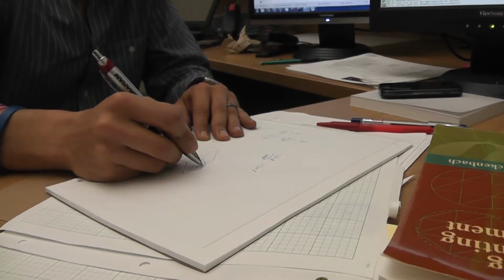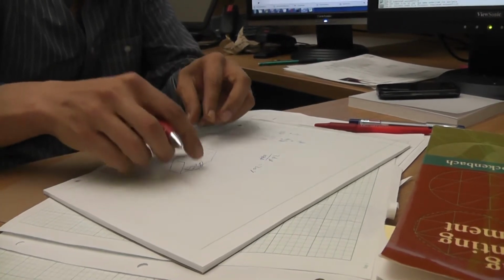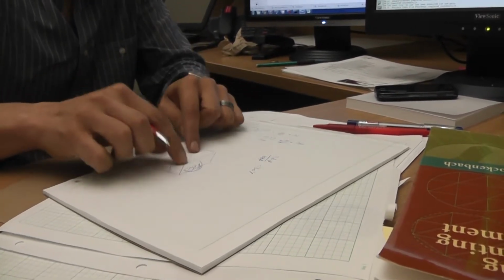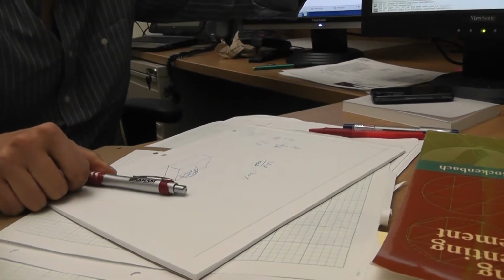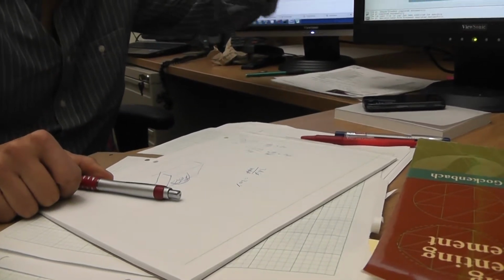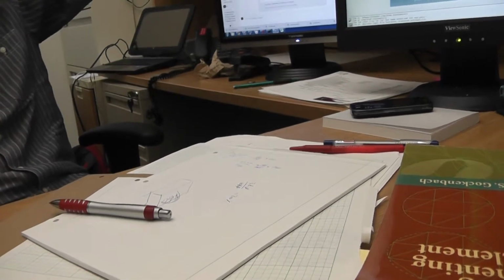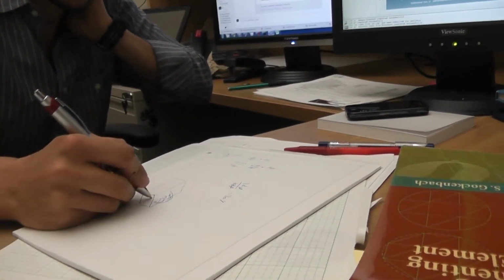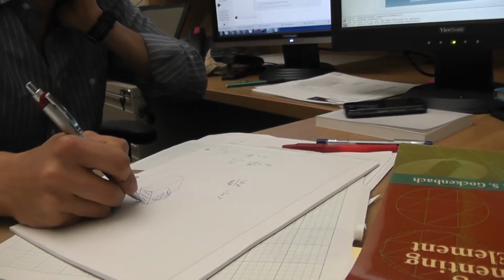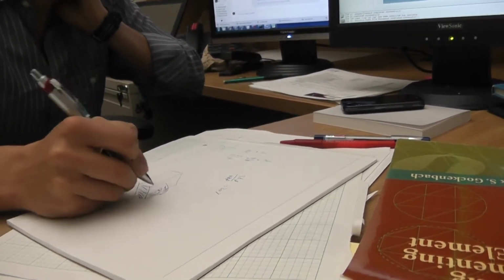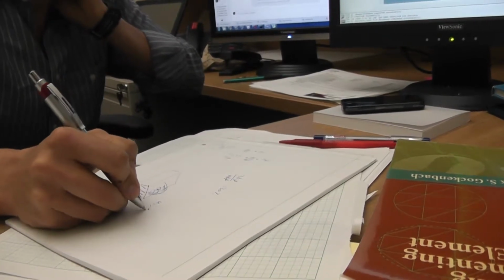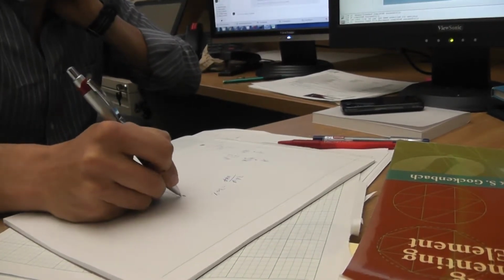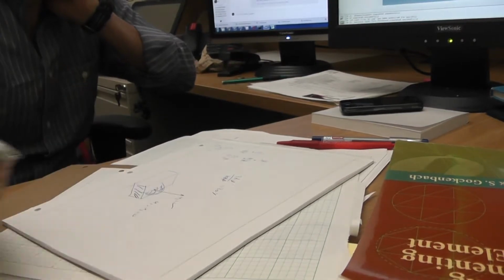I don't know how you're going to attach it. But design this plate, and based on that design of this plate, then you apply the load here. Okay? Let's say I'm assuming that I'm applying the load on the surface. Wherever you apply the load, you make sure you fix U1 and U2 equal to 0 and U3 is equal to displacement.